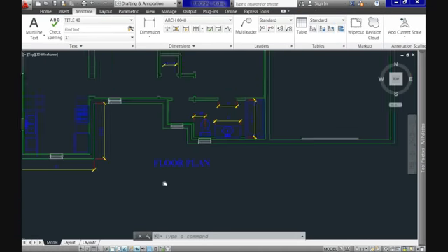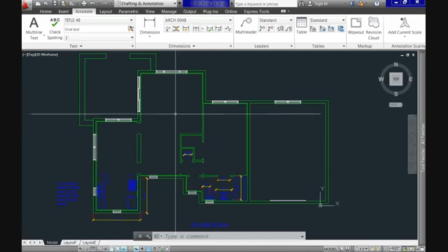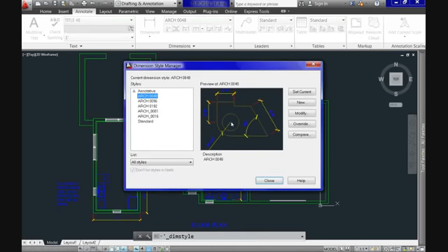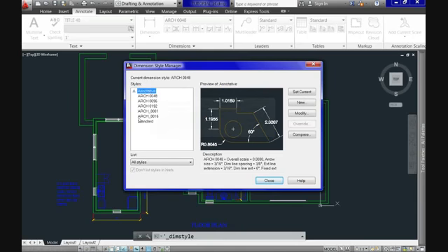Click the diagonal arrow and the dimensions panel or manager will come up. Like with the text styles, on the left we'll have the available styles. Also, the annotative and standards are the default and the rest are user defined, which means I created them. On the right, we have some options like compare some of them or modify an existing one. In our case, we'll click New to start a new style.